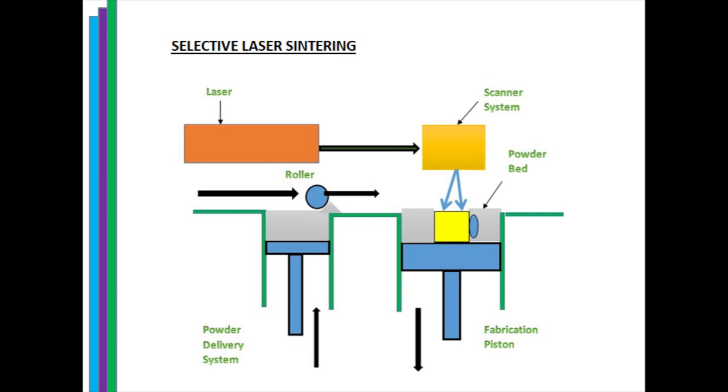Unlike other methods of 3D printing, SLS requires very little additional tooling once an object is printed. It means that the objects don't usually have to be sanded or otherwise altered once they come out of the SLS machine. SLS doesn't require the use of additional supports to hold an object together while it is being printed. Such supports are often necessary with other 3D printing methods such as the SLA method or FDM method, making these methods more time consuming when compared to SLS.